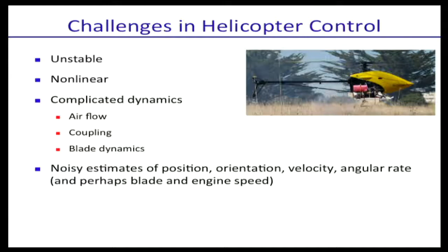The reason the dynamics are complicated is largely the airflow. Airflow is very difficult to model. Fluid dynamics is also very expensive to simulate. It's not practical with any of the current systems to fully simulate the airflow around the helicopter in a reasonable way in real time, because that really would be the full state of your system. It would not just be the helicopter, it would also be what all the air is doing around your helicopter. That means solving partial differential equations in real time, and that even assumes that you can measure the initial state to get a feel for what this system starts from and simulate. So it's very difficult to handle that.